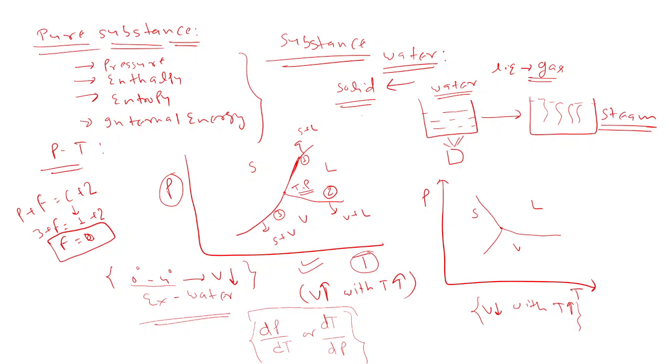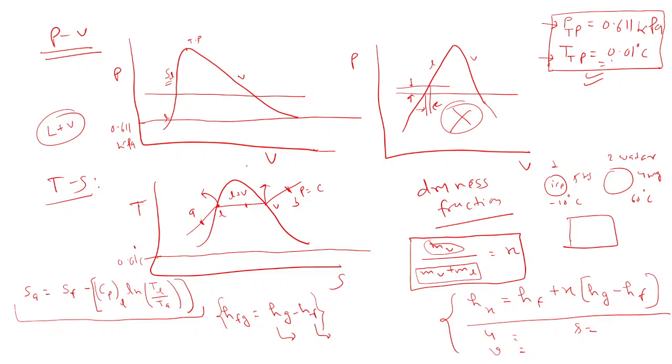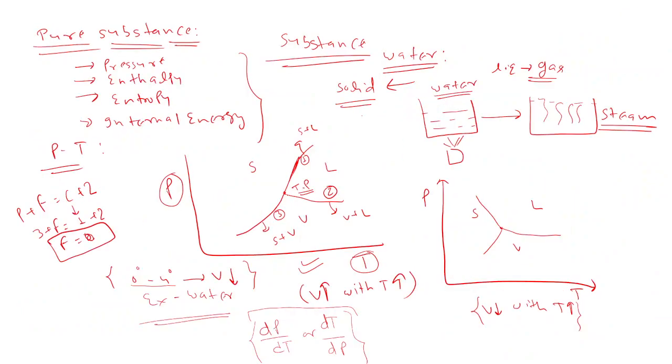Pressure would be the same but volume increased, meaning some part of the liquid converted to vapor at the triple point. So volume changes but temperature and pressure won't change. That's why entropy and volume are not constant, they may change, but pressure and temperature are constant. So for the PT curve, the triple point is a point.